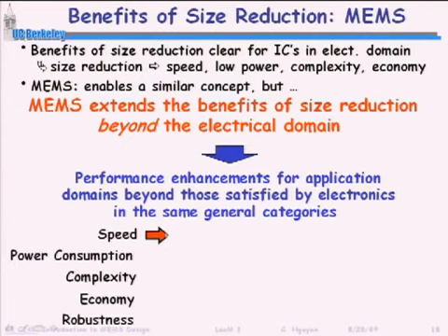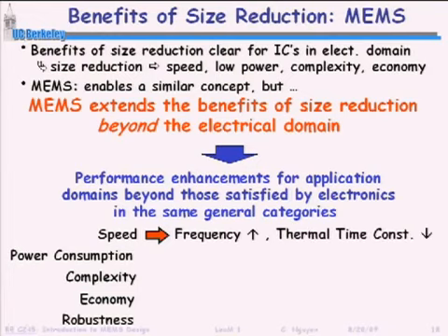You make something smaller. If you have to heat it up, you can heat it up instantaneously now. Okay, you're not waiting 30 minutes or so for this oscillator to stabilize. It happens in milliseconds, just because things are smaller. Power consumption. Actuation energies go down, heating power. That example again, if you have to heat something, and a lot of sensors require heating. Okay, to do the sensing correctly, like gas sensors, it's best to heat these things. Well, if you have a macroscopic version of it, you're going to be expending a watt of power or so. The MEMS version, maybe milliwatts of power.